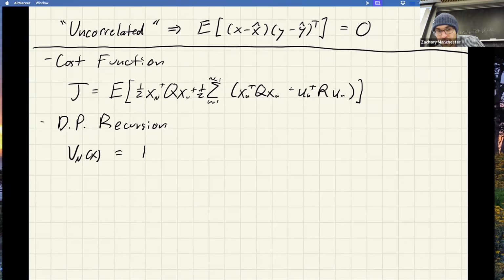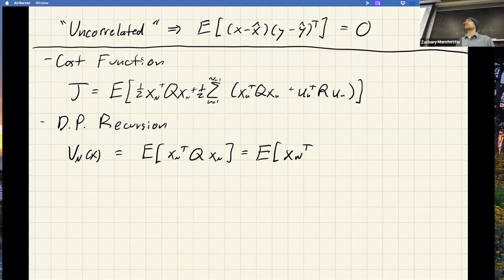So we have the terminal cost at time step n, just like before, with an expectation around it now. Just like in LQR, we assume the cost to go is quadratic and stays quadratic because of linearity. We call the cost to go Hessian P, and we start with Pn equals Qn, just like before. All that carries over.